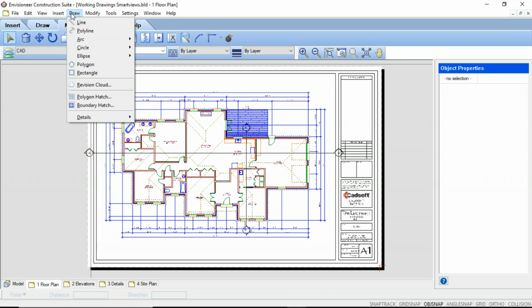Just a note here as well. Remember that the extra lines and hatch that you add here are not linked back to your model. So any modifications that you make here will not be reflected in your model view or any subsequent views that you insert. If you want to make changes other than line work changes, it is best to make them in your model view first. Changes you make in your worksheet view will be mainly line work changes in that worksheet view.